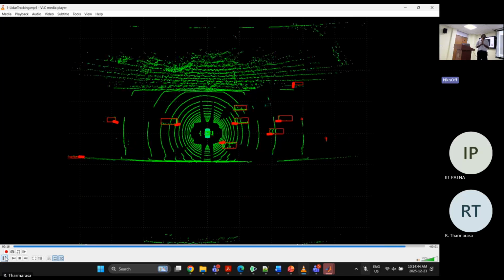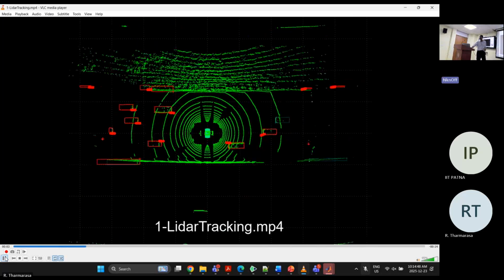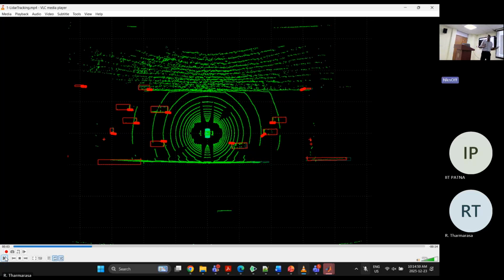So in this course, for us, the input is the green dots. Right? When we talk about tracking, LiDAR gives detections. Even before you come to the detection, there are a few steps, right? It generates the raw data. From that, you want to get the detections, which we usually do using CFAR, constant false alarm rate, to generate the detections.